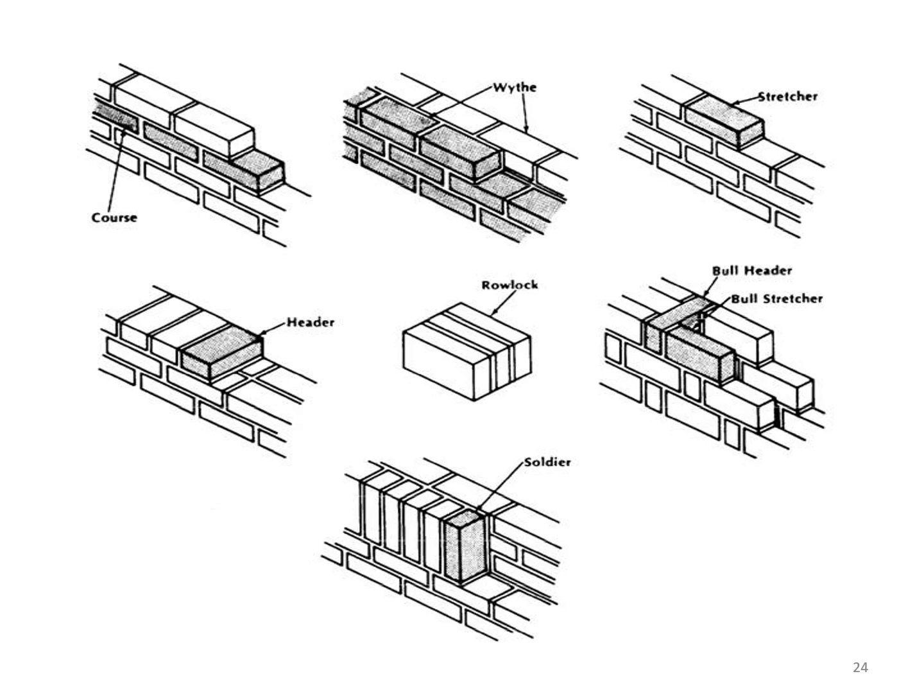What it is, the joints. Vertically, joints are staggered one over another. Now there's a reason for that. It provides a lot more strength. Now let's take a look over to the row below that on the left in the middle, and you can see that you could do what's called a header course, where you're really using the brick to bridge and close across 2 different rows of brick when you're doing a double brick wall like that. So that's an important thing too.